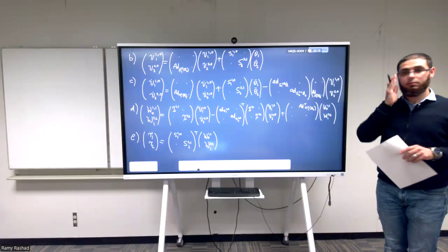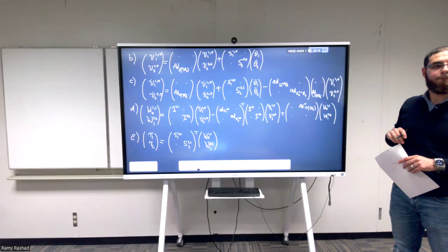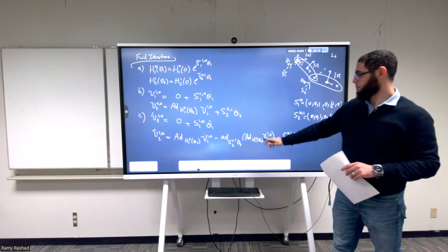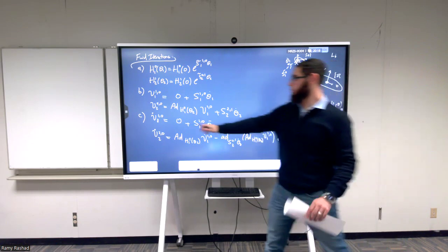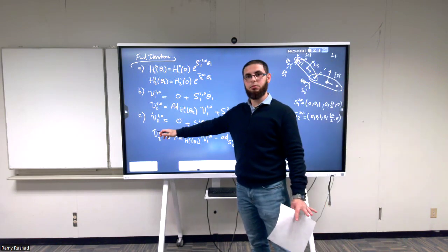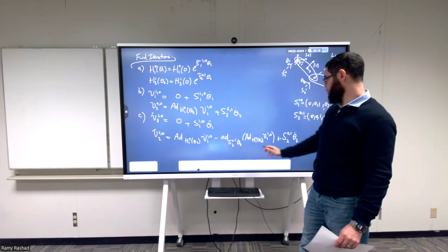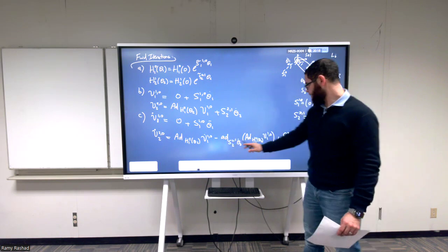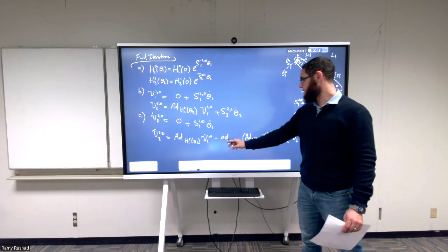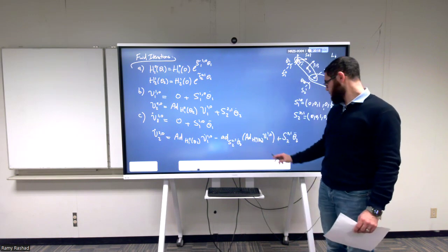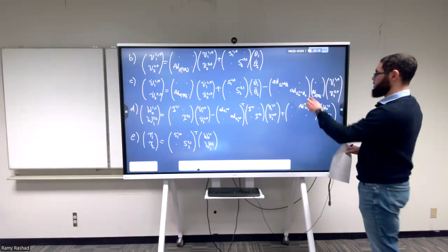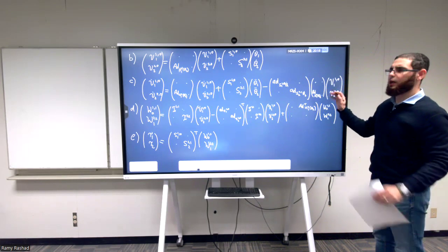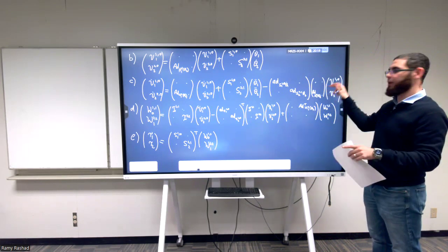Yes? The V dot? I'm just rewriting the same equations. Nothing new. The small adjoint, this one. So you see, this expression is the product of three terms: the small adjoint, the big adjoint, and the V1, in this order. So this is a 2 by 2. Again, not a 2 by 2, but I mean a block diagonal 2 by 2 matrix.